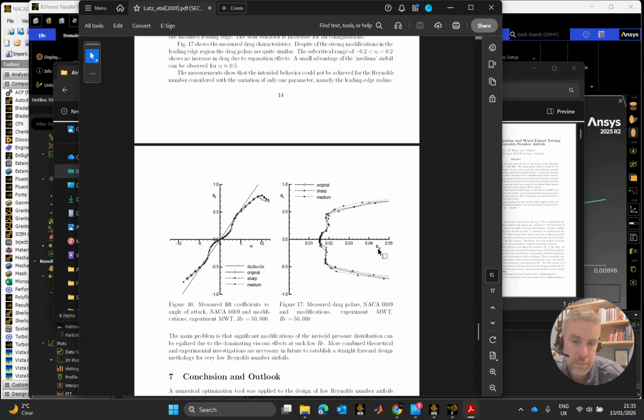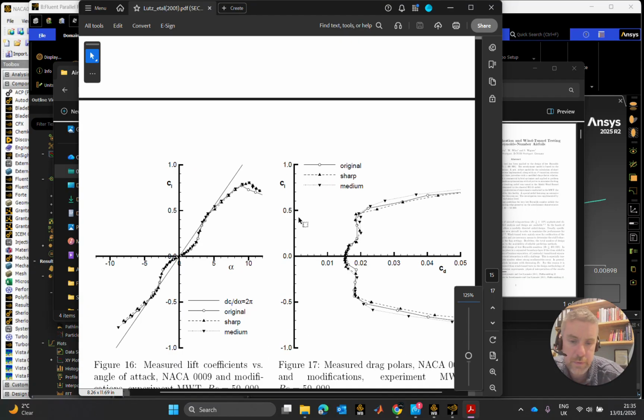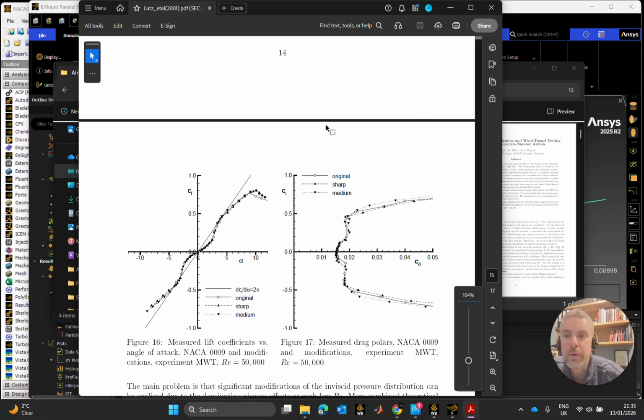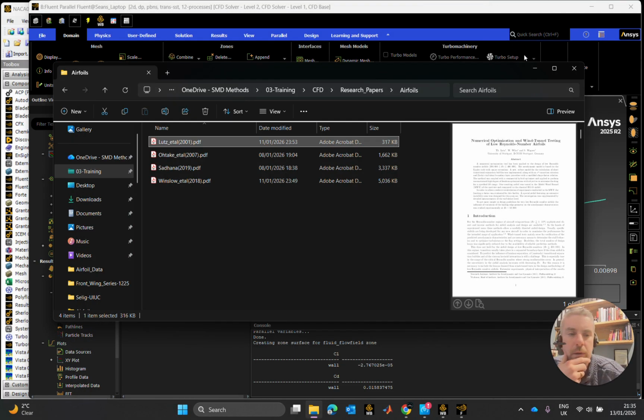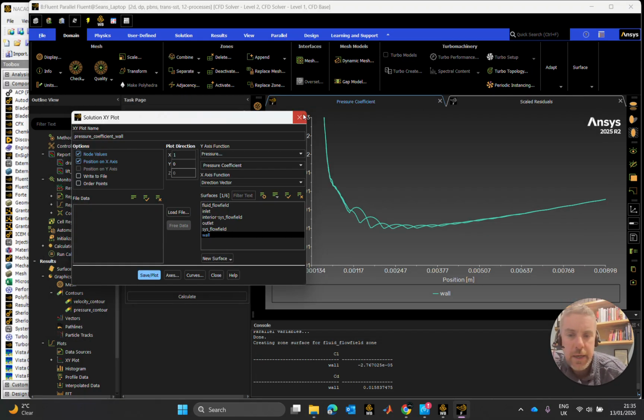There's a nice one there, CL by CD. We could plot a CL versus a CD, even though maybe it's just one scalar value, a CL over CD. I'll do CL over CD just now, how to write the named expression and calculate the CL over CD in this one, and then we'll stop the video and move on to the next one, where we'll set up a couple of other field variables, named expressions, and put in a few functions to help us populate a parameter table from which to run our mesh independent study.